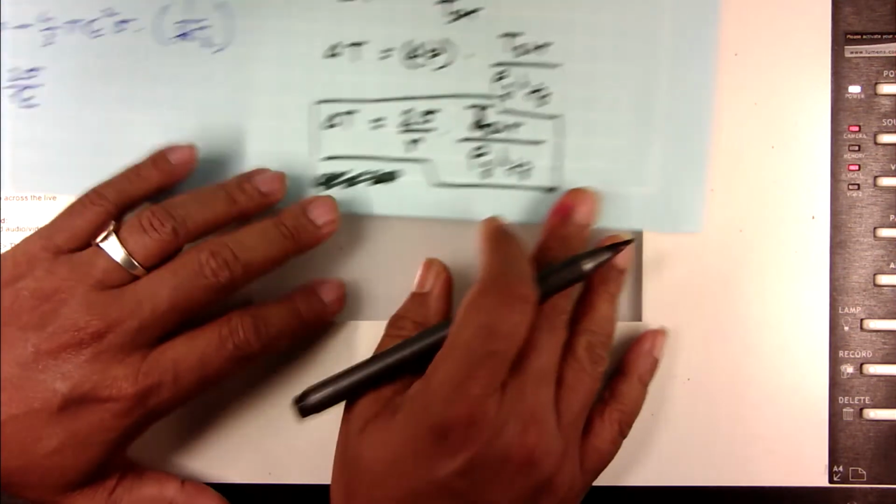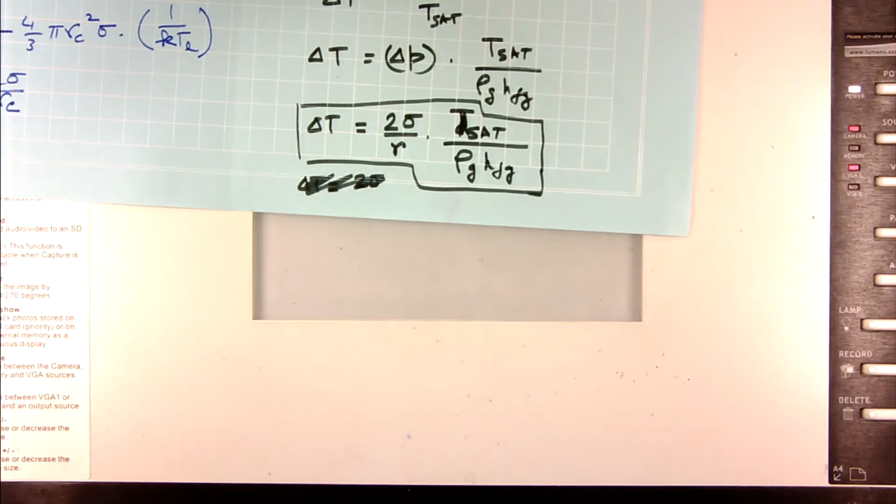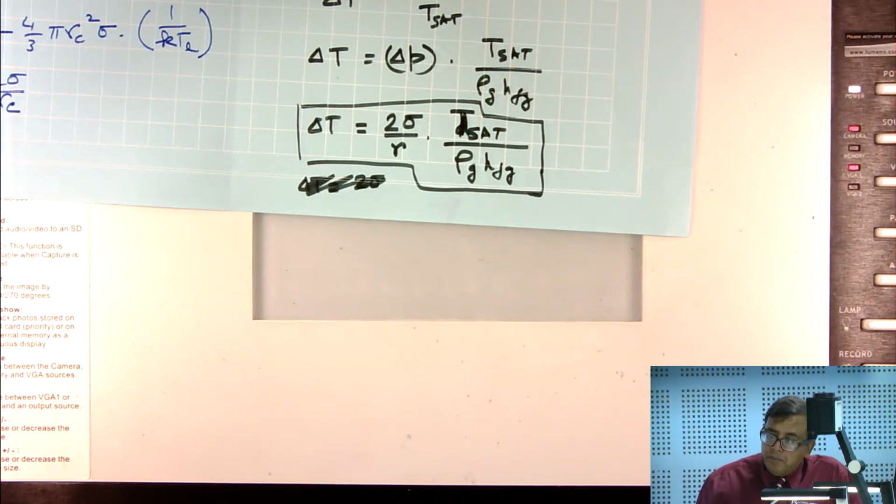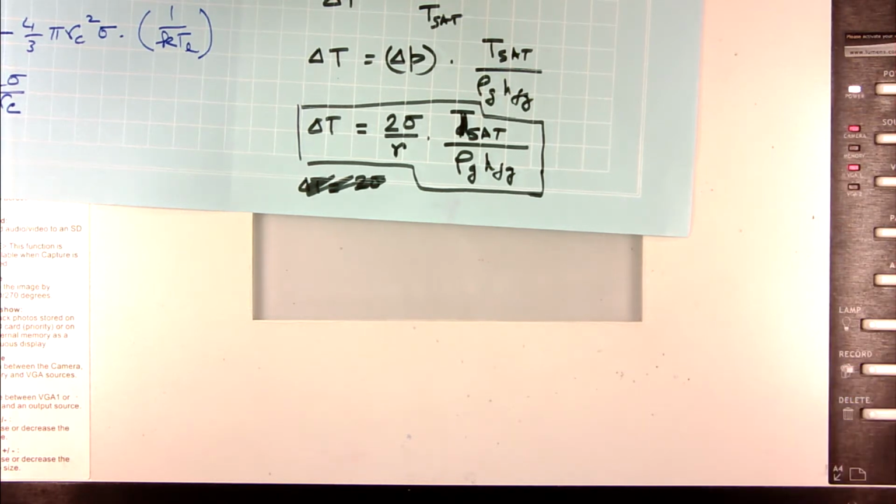Now, how does the bubble nucleation occur on the heater surface? Okay. So, for that you need to consider how the heater was manufactured. Okay. So, for typical industrial heaters that are usually made out of copper, what they typically do is they cast the copper into blocks, right, and then they let the liquid copper solidify.